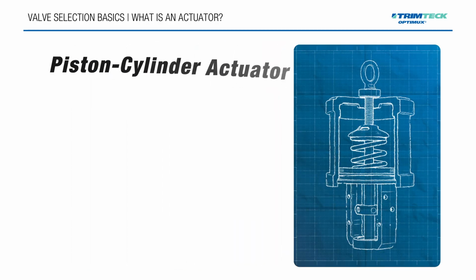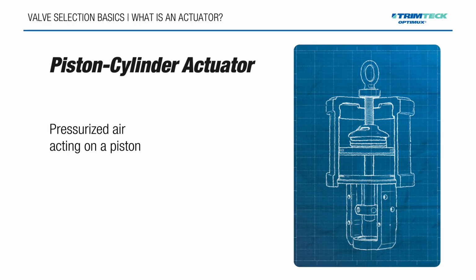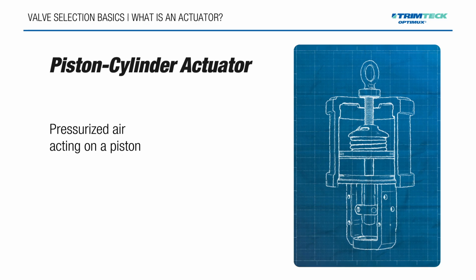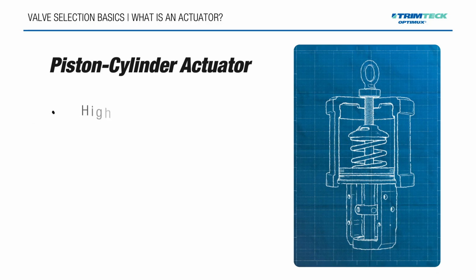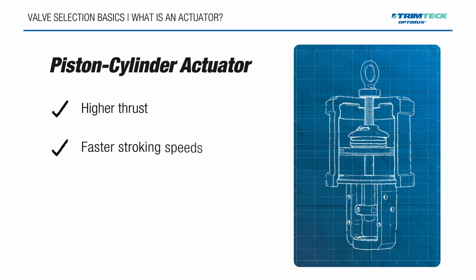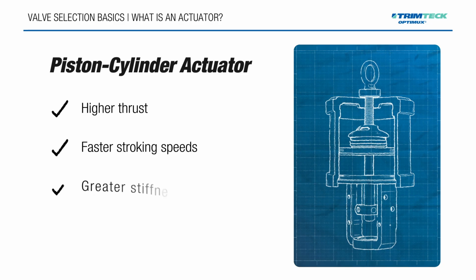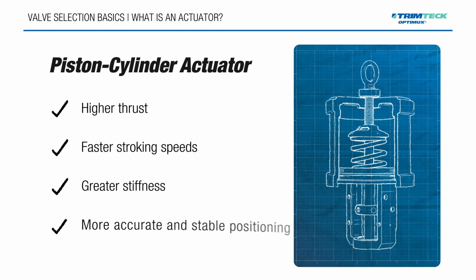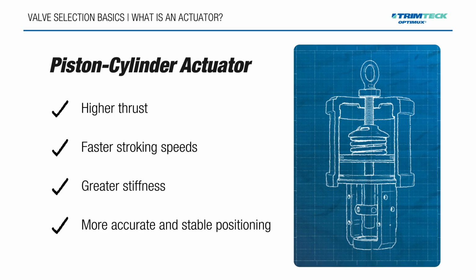Piston-cylinder actuators use pressurized air acting on a piston to generate motion. Compared to diaphragm designs, they provide higher thrust, faster stroking speeds, greater stiffness, and more accurate and stable positioning. This results in improved control performance, minimal hysteresis, and excellent linearity.